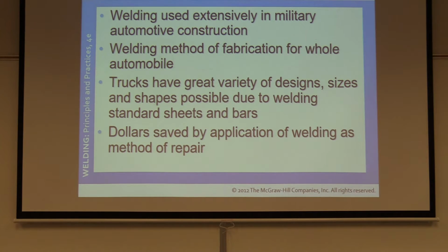Now, engine blocks a lot of times are made of a cast material. However, you may be able to braze weld them back, torch braze them, okay? You can gas weld steel, you can use bronze. There's different things you can do with different materials to be able to help the fusion and welding processes.